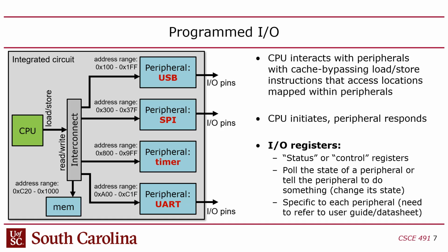Now, how do you load or store in C? I mean, we know how to do it in assembly. You just write a load instruction. How do you do it in C? Well, in C, you're assuming you need the compiler to translate your C code to loads and stores. How do you guarantee that it's going to do that? Well, one way is through a dereference, star.